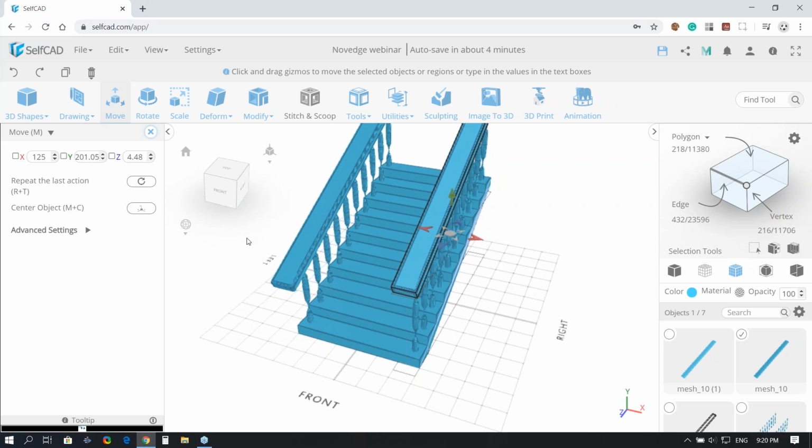Okay, so now that we have these two selected, I just want to make sure it's actually intersecting. It goes in, so I'm going to the wireframe to see if I need to move it down a little bit. It actually looks done nicely. It's well done. So now I can just select these, and I'm going to make a Boolean of them and combine them. Okay, so this is done.